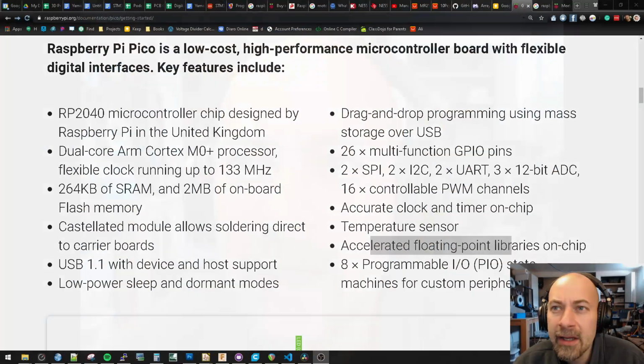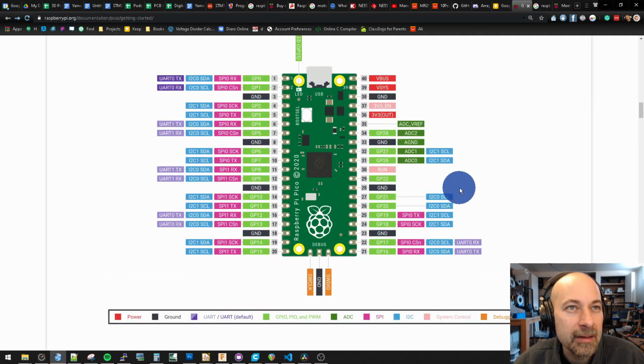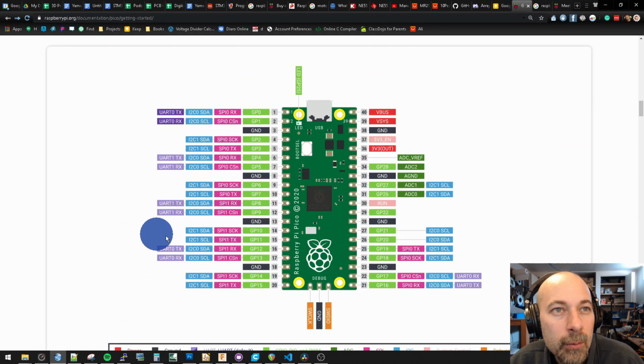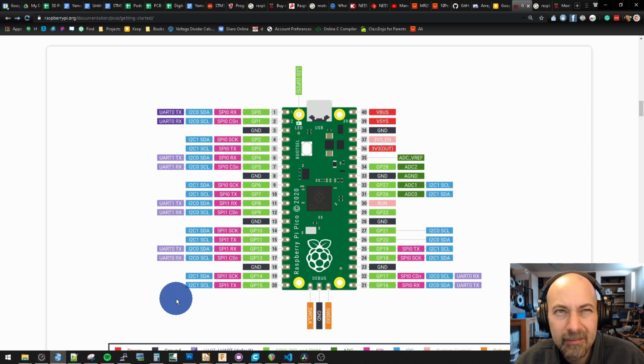So here's another cool one. This is kind of the stuff that doesn't get talked about as much: you have multiple pin out options. Let's switch it back to the old thing. Here we go. When you look at the pin out on this thing, you can see that we have SPI 1 clock on GPIO 10, which is number 14, I guess you can call it pin 14. Then we also have SPI 1 clock on pin 19. Of course, it doesn't do both. You pick one. And this is common with a Blue Pill. Blue Pill could do this in certain instances.